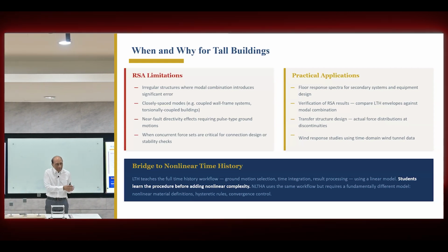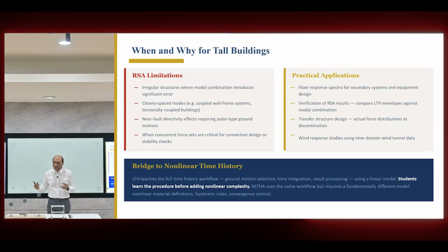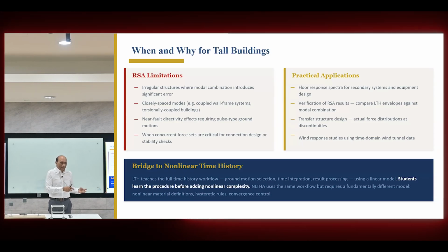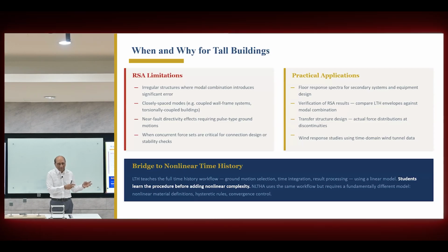So for the nonlinear model, you need reinforcement to make the model. So where does it come from? Where should we get it from? We have to get it from somewhere. So response spectrum is the starting point where you can do the response spectrum based design, get the reinforcement and sizes, and then move on to the next stages. So it becomes an important design step.